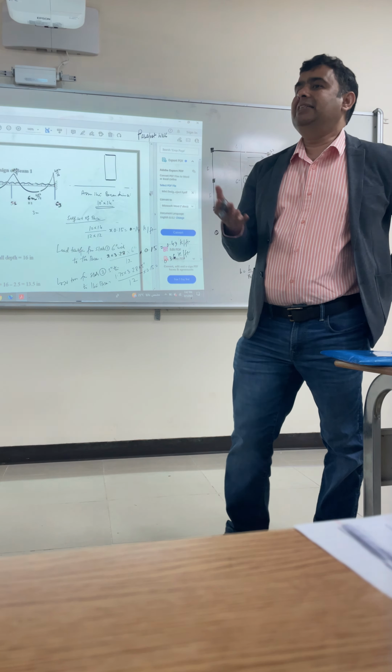It is not by default. Because your building is a residential building, we have seen the formula for calculating the live load for homes. But here it is different, because we are designing a roof. Our building is a one-story building, so very rarely will people go to the top of the slab. Nobody will go to the top.